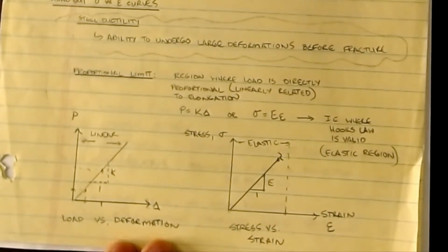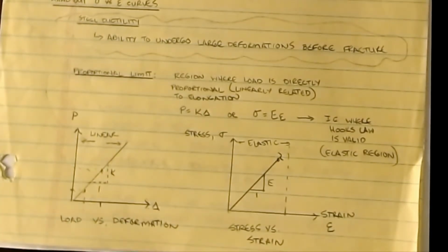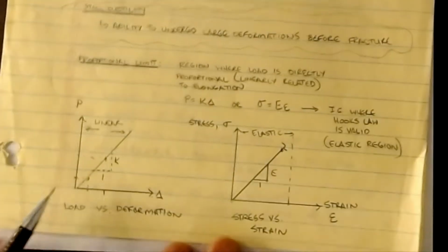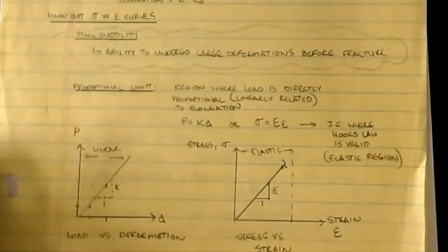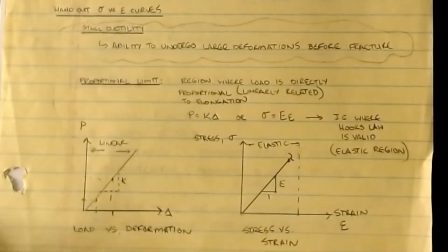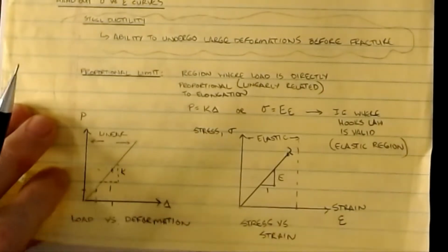We don't want a case where, as deflections get larger and larger, the load is not in the same ratio. So this is going to be our definition of linear load versus deformation. Now, structures like cable systems, even suspension bridges to some degree, are not linear structures. They still function, but they have to be designed a little bit differently than what I'm going to show you. So we're looking at relatively simple cases in this series as we explore the LRFD equations.